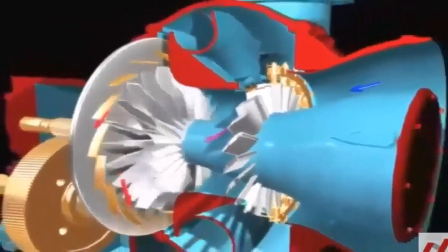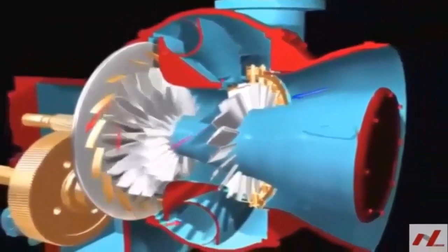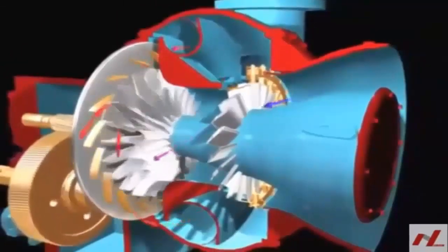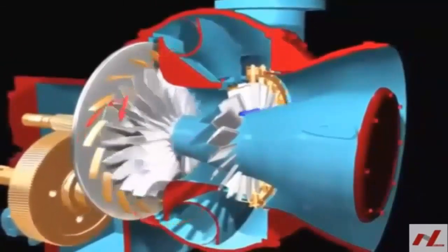They are machines that provide us with a fairly high level of efficiency. The efficiency of these machines can reach, as we said last class, up to 0.3 kilowatts of electrical consumption for each refrigeration ton. Of course, it will depend on the configuration of the machine and also on the installation of the chilled water plant. We can do nothing with having a very efficient compressor, a very efficient chiller, but if the installation of the chilled water plant is not correct,